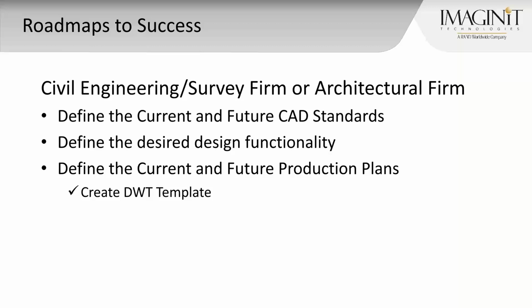As I said, the first thing we do is create the DWT, and that's the CAD standards. Again, I've said it probably five times: levels to layers, line types to the new line types, cells to blocks. All the fundamentals of the CAD standards are held within the template, and that template allows us to move forward and recreate the look that we're looking for.